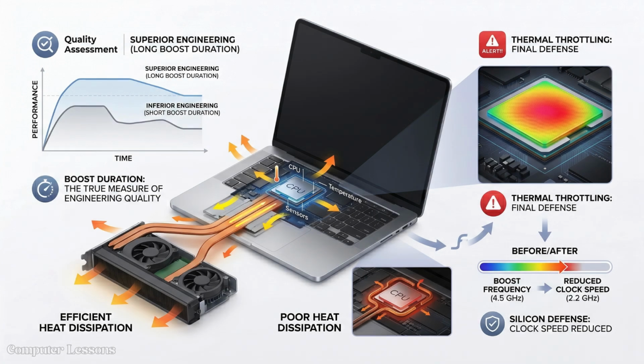Thermal throttling is the final defense against silicon damage, reducing clock speeds when temperatures reach dangerous levels. Engineers aim to delay this process as long as possible through efficient heat dissipation. The duration a laptop can maintain its boost frequency is a true measure of its engineering quality.